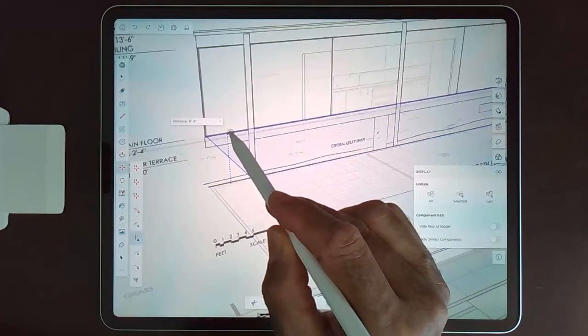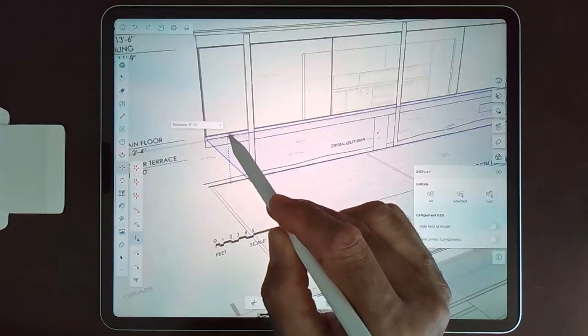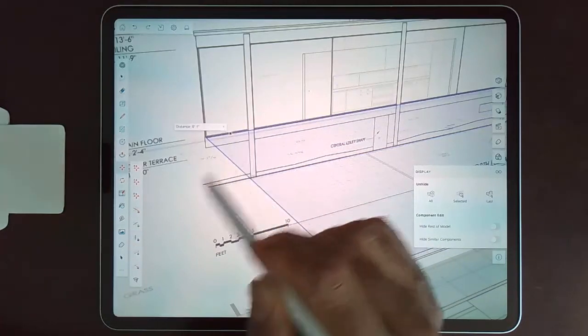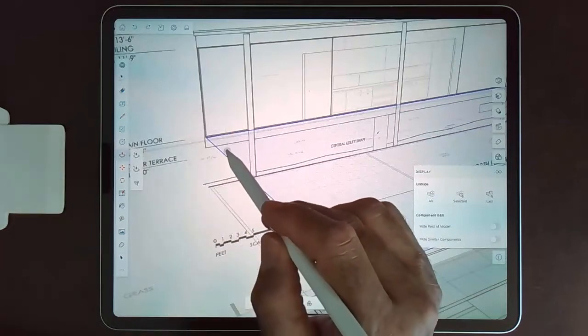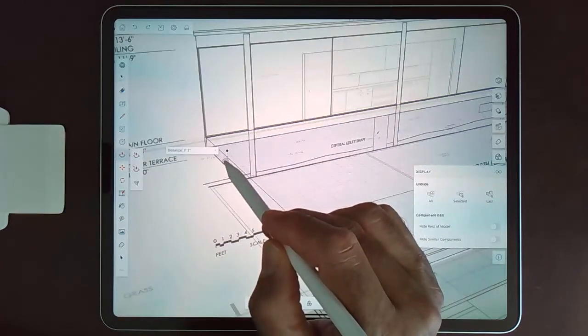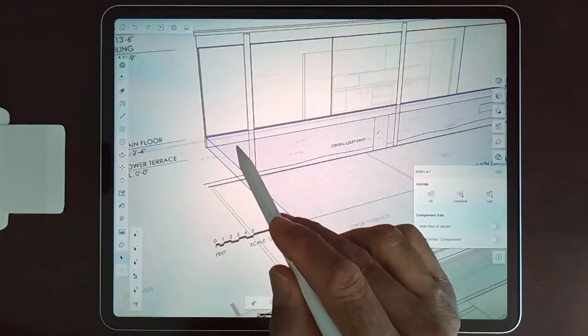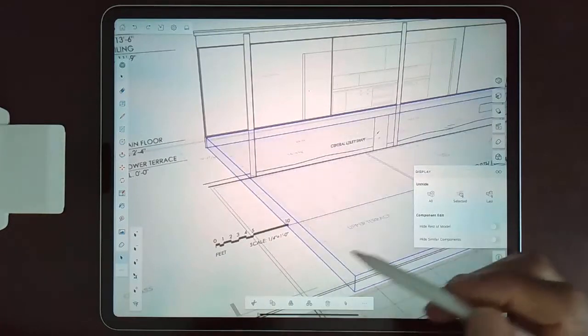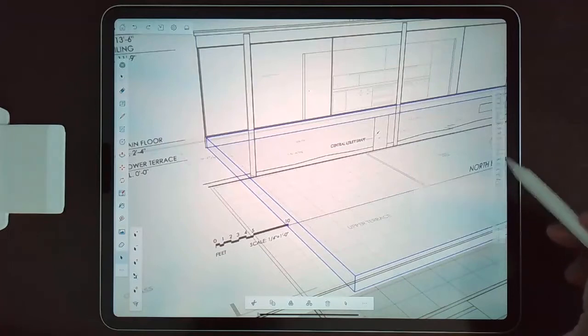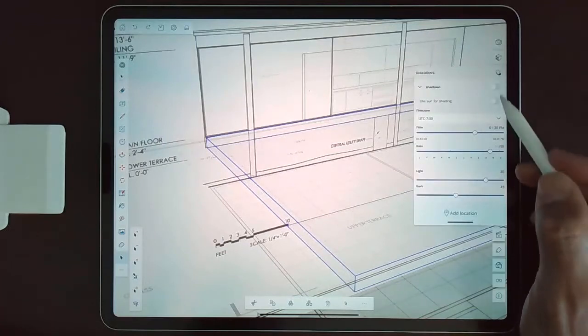First, we're going to bring it up to the right elevation. Because we have our snap set to 1 inch and our precision to 1 inch, we don't have to worry so much about where that is in space, other than making sure that it's close. And then extrude it down 14 inches, which we've now seen here.